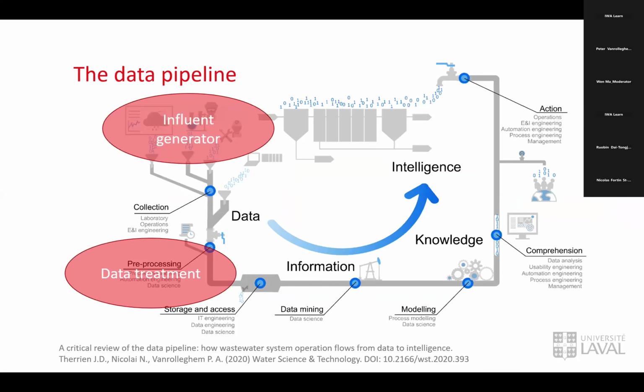I want to give another example of where we used machine learning methods to help come to decisions. And we know that wastewater is a complex thing. It changes all the time. There's rain effects, there's seasonal effects, there's industry discharges. All these things happen and make the wastewater very time varying. So what we want to do is to use information from the past, some historical data, and use it then to create a generator of influent properties, flows, and concentrations on different time scales.